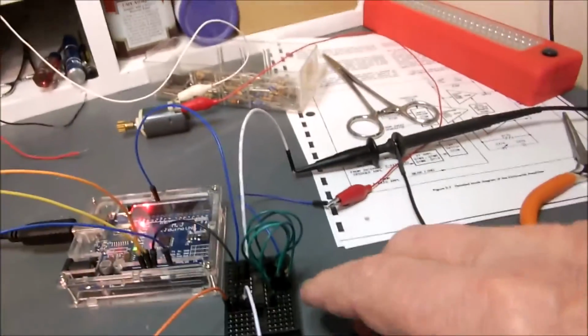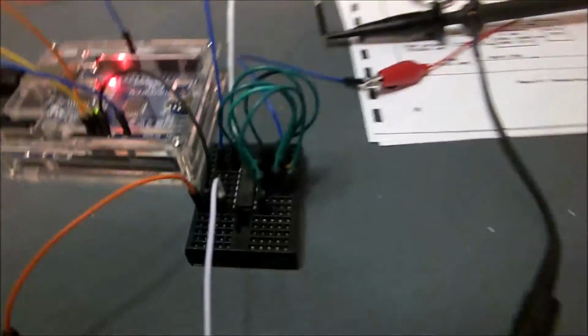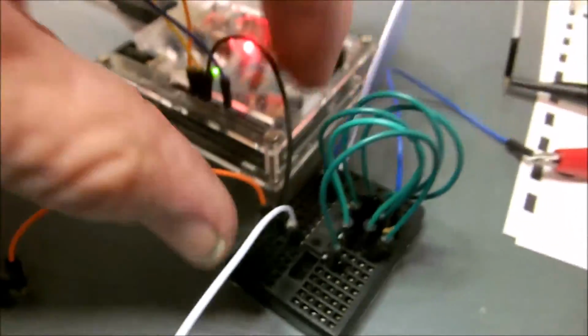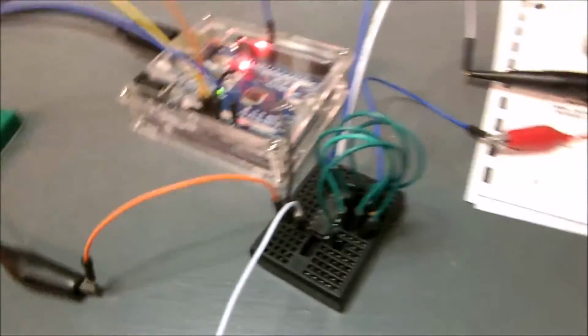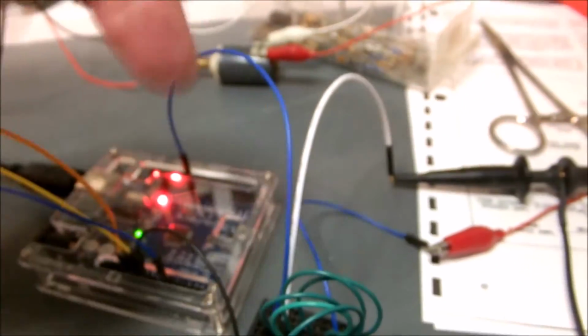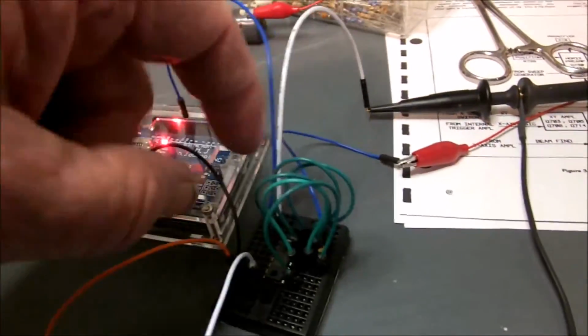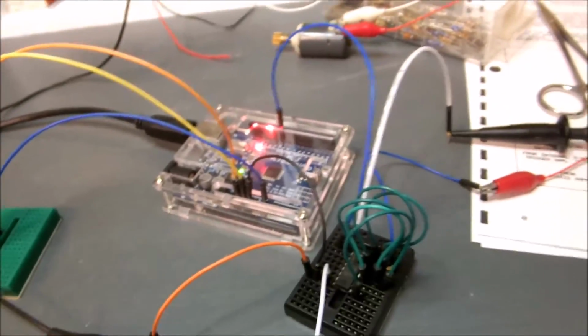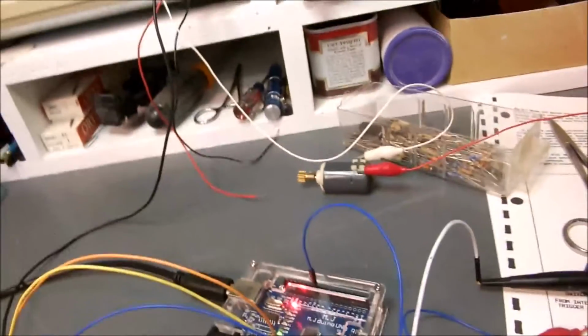So we're employing a little device called a ULN2003A. It's an IC here that's really a series of some Darlington pairs, and we hooked a few of them in parallel to get enough current to drive that motor. But we'll run our PWM, our pulse width modulated signal, into the input of the 2003, and the output will then provide more current, and it'll drive our motor for us.